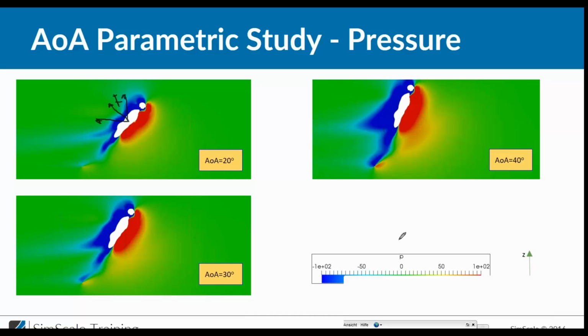We can see that this large bubble in front of the athlete is like a force that will push you back, and because of the low pressure behind the ski jumper, this blue region, we can see that this pressure difference, this delta P, will create a force directed against the free stream, and this athlete will be pushed back, and this is what we call drag force.